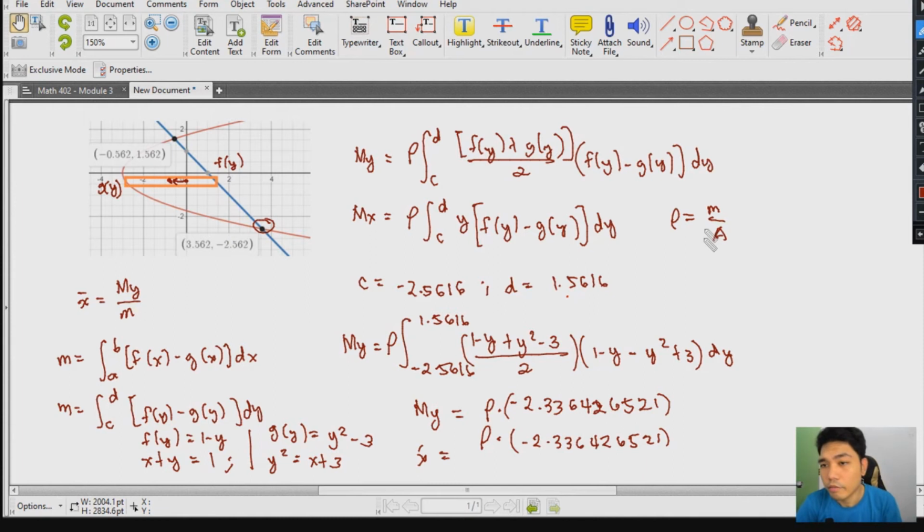So if you have the mass, that is simply equal to the density times the area, and x bar is divided by your density times area, which cancels out the unit density, so we're left with the area. That's why you can represent that mass in terms of area. But if you want to do that, you have to make sure that you're canceling out the density portion here.